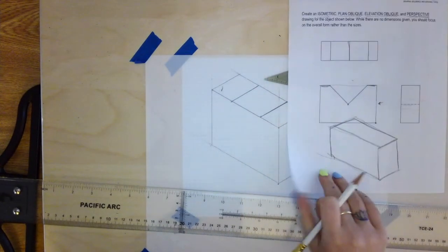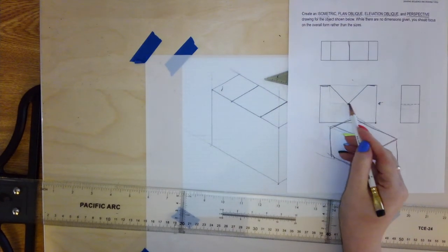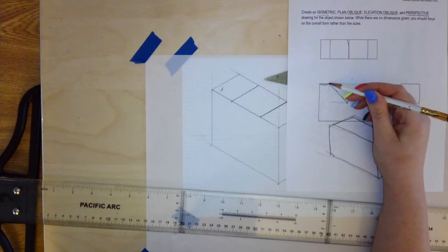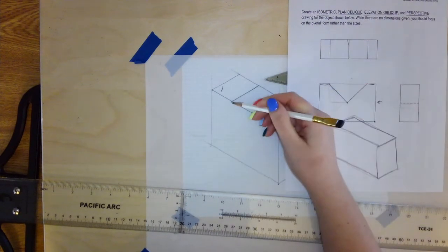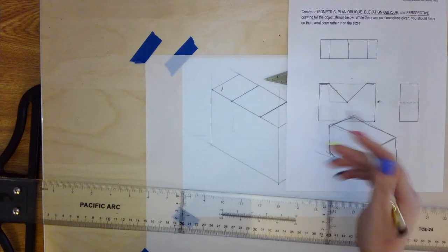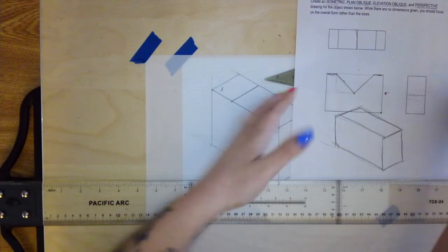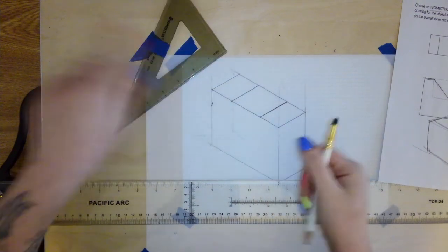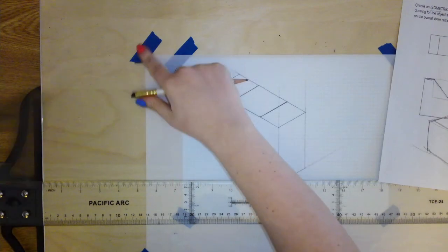Now, in my front view as well, I go down and over, but not necessarily directly down and over. Because this is what we call a non-isometric line, since it has that angle to it, I'm going to project straight down, project over at 30 degrees until I find exactly where I would want that point to be. Now my drawing is going to look a little bit wonky, because I probably should have either gone longer with the length or not put these as far out, but it'll get the concept across.